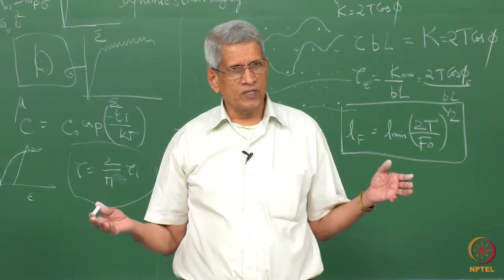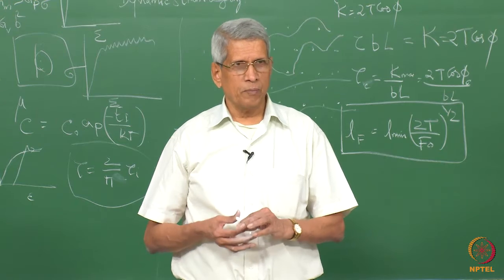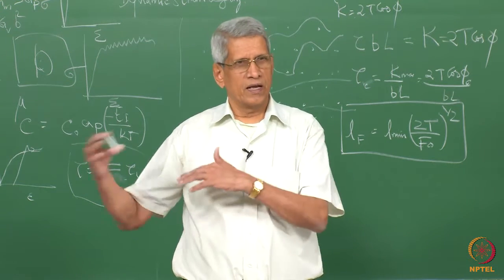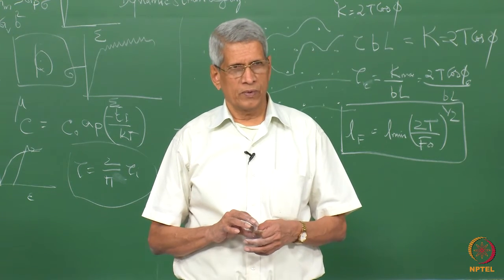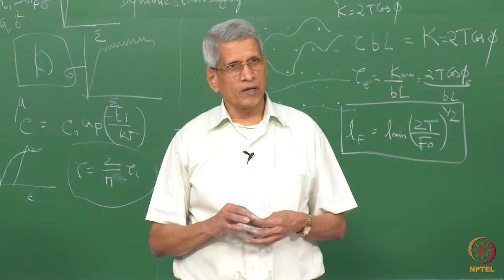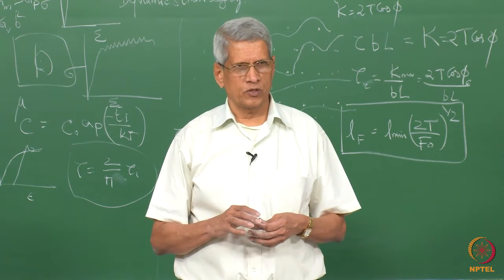The other aspect is that dislocations can interact with the grain boundaries. I don't want to bring that in at this particular level. That's also one thing which has to be done, because that also gives rise to hardening. That's what the Hall-Petch relationship corresponds to.